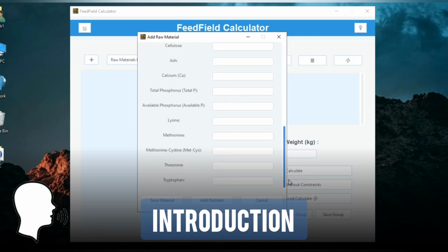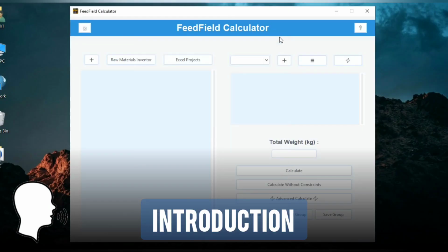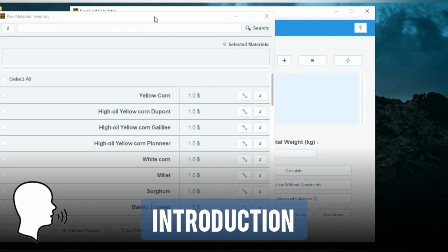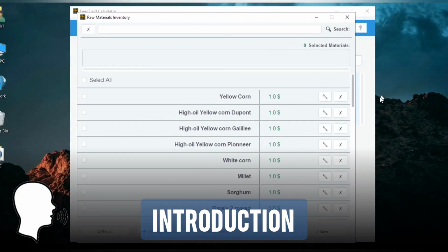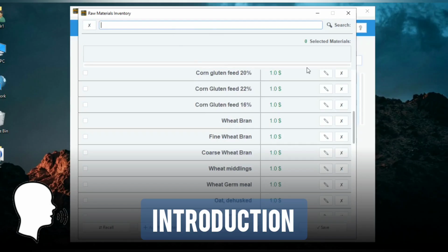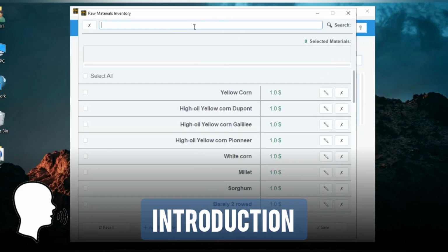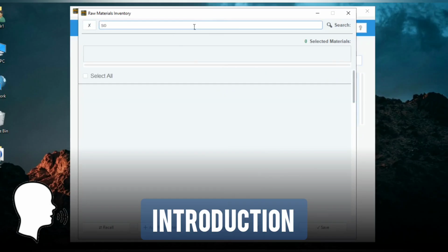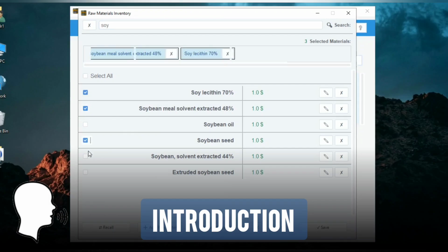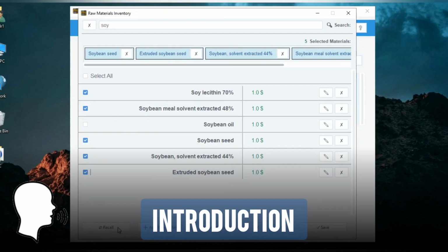This is because these methods rely on human trial and error, unlike computer-based linear equations, which is what this program uses. The program operates using linear equations. It evaluates the chemical analysis you require, analyzes the available raw material data, and then selects the optimal raw material proportions that achieve the required chemical analysis at the lowest possible cost. The only scenario that guarantees the lowest possible cost is the one chosen by the program.